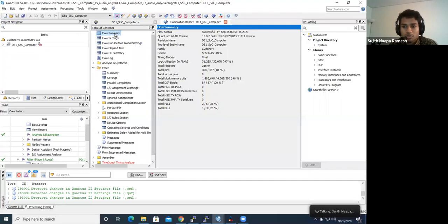That was probably built using the logic blocks. The DSP blocks do have, Bruce, you can correct me if I'm wrong, 27-bit hardware multipliers in there. Correct. There are 27-bit hardware multipliers and there are 18-bit hardware multipliers. In Lab 1, you used the 27 bits, and in Lab 2, we're going to use a whole bunch of the 18 bits. Two 18 bits are bolted together to make a 27 bit with some extra logic, so you can do one or the other, but not both.